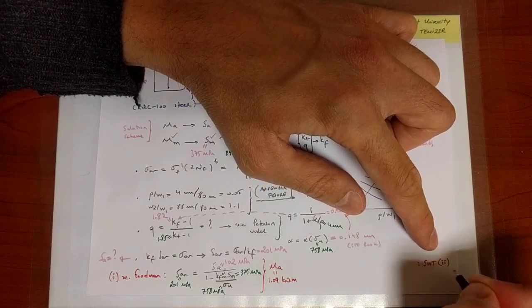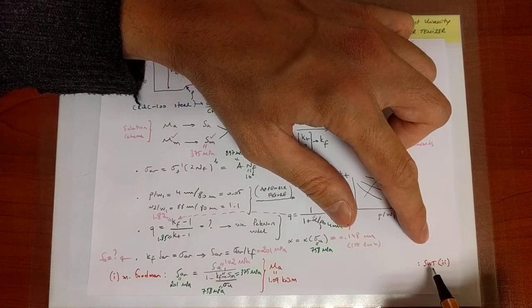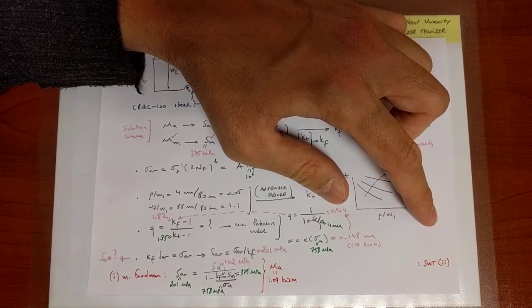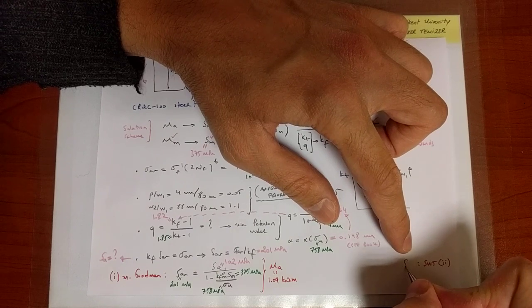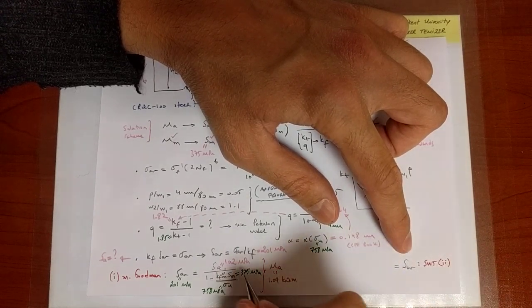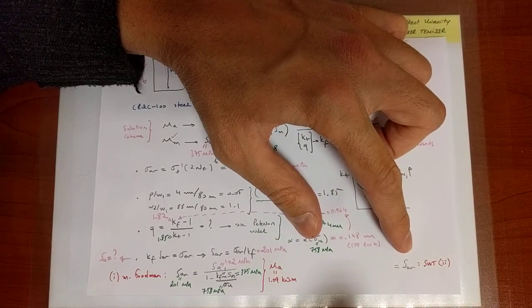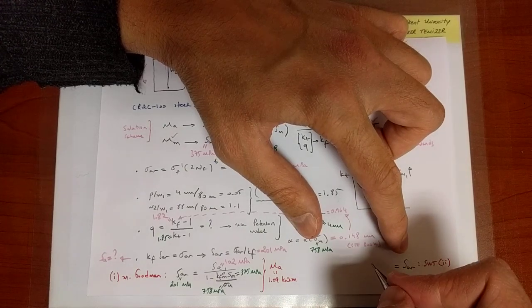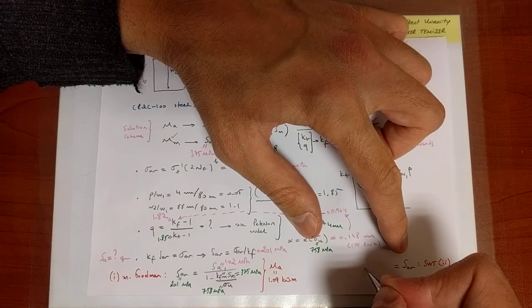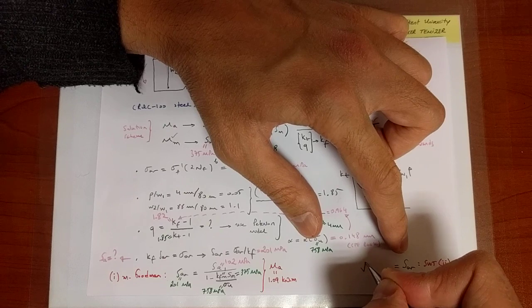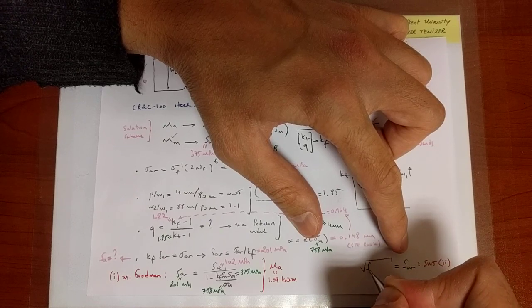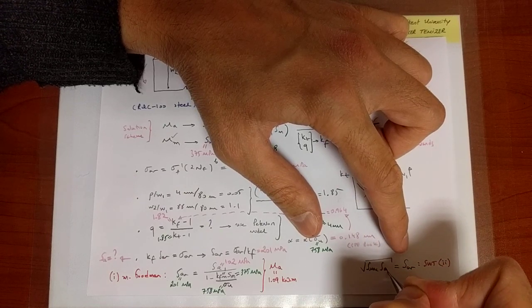So let's write it from right to left. The SWT approach is going to say that SAR is again a function of the mean and the alternating components of the nominal stress, but in this case that relation is through the square root of S max times SA.